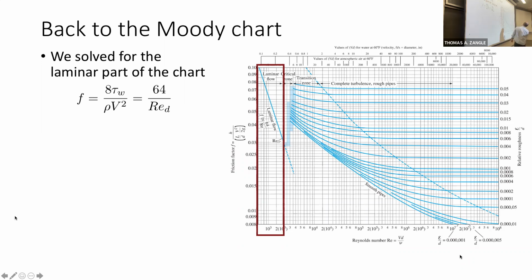So I guess those are in feet per second. But if you knew VD in feet per second was 20, you could just read that down and come up with your Reynolds number of 1.8 times 10 to the fifth. Your definition of relative roughness is on here as well, epsilon over D, along with some different values.